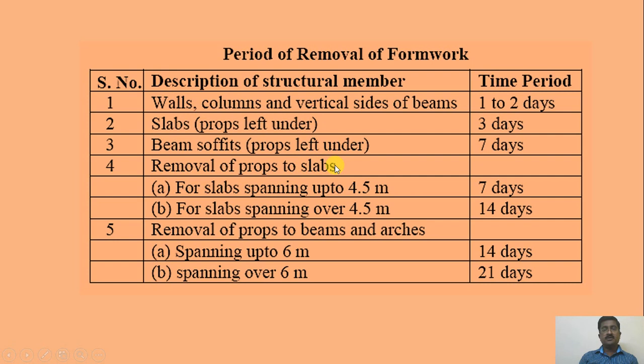Removal of props to slabs: for slabs spanning up to 4.5 meter, you can remove after 7 days. For slabs spanning over 4.5 meter, 14 days. Removal of props to beams and arches spanning up to 6 meter, 14 days. Spanning over 6 meter, 21 days.